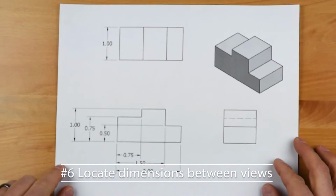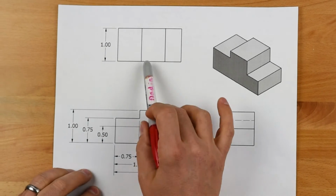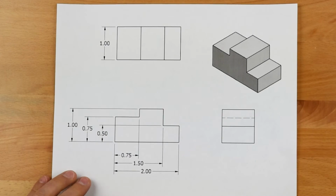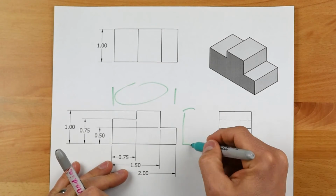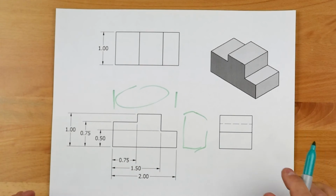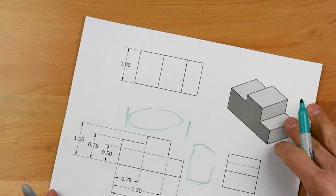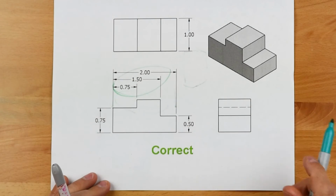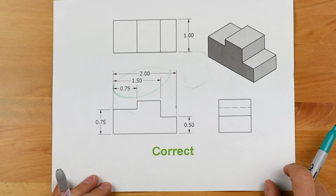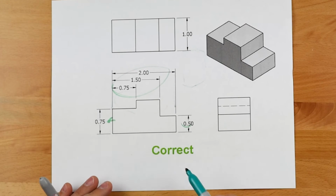All right, in this example here, just as a general guideline, you can see most all of the dimensions are on this part, but what we really like to do is we prefer to find ourselves dimensioning in between the views if possible. So we're really trying to put dimensions here, dimensions in here, if we can. Now that may not always be the case, and we'll see this in this example as we move to the side. That's more correct, is that we've shifted all of our dimensions into the in between the drawings. We have it here, but we do make an exception for this 3/4 of an inch.